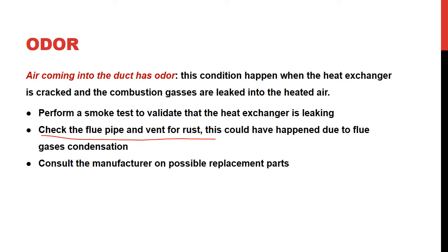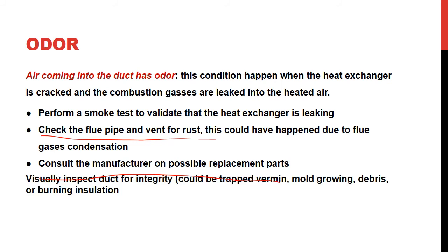Consult the manufacturer for replacement parts. If you found out that the heat exchanger is actually failing, sometimes you can change the heat exchanger, and other times you have to change the entire furnace. So check if that's a possibility, but under no circumstances should you fix the heat exchanger. I mean, do not try to patch it, but you can replace the entire heat exchanger. Again, it's a liability issue, and carbon monoxide is very fatal, so be careful with that.